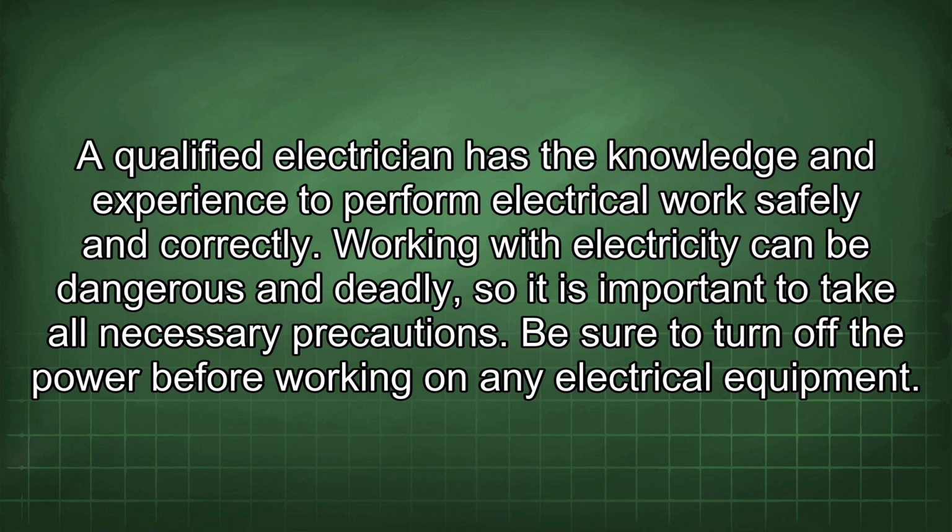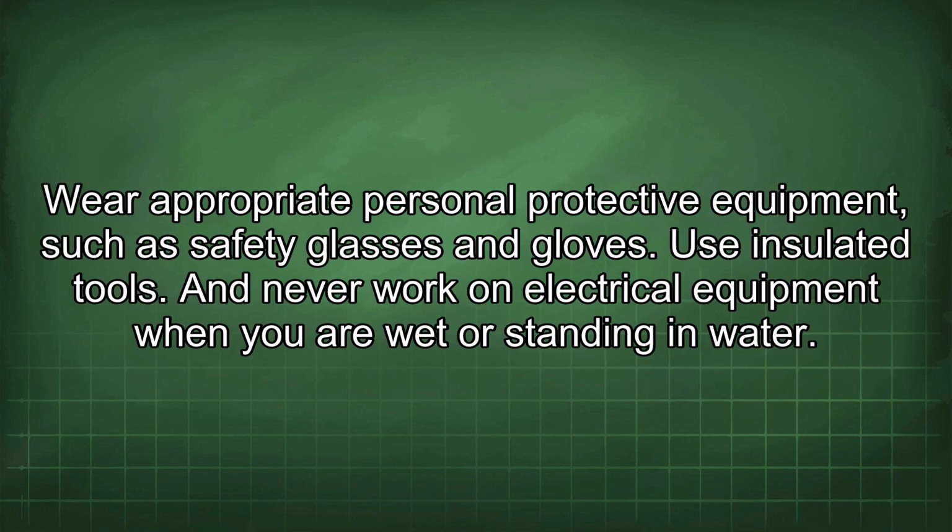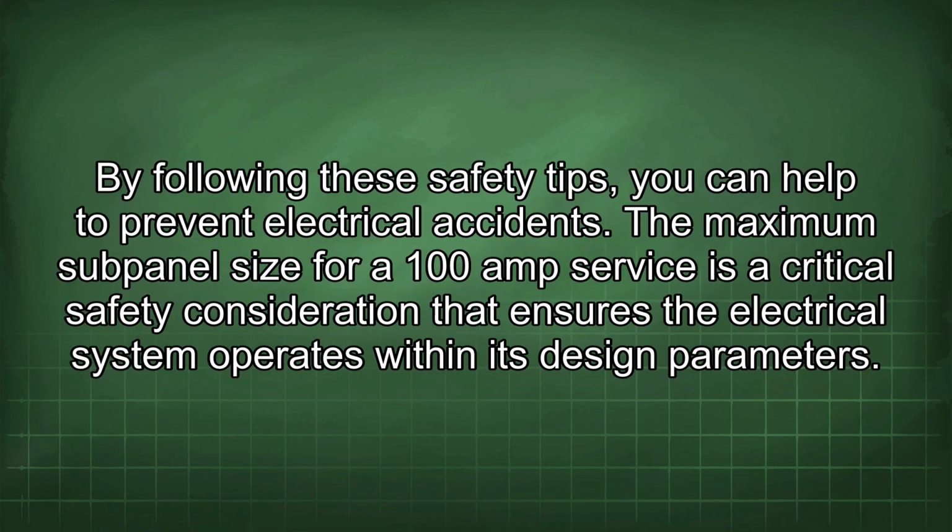Be sure to turn off the power before working on any electrical equipment. Wear appropriate personal protective equipment, such as safety glasses and gloves. Use insulated tools. And never work on electrical equipment when you are wet or standing in water. By following these safety tips, you can help to prevent electrical accidents.